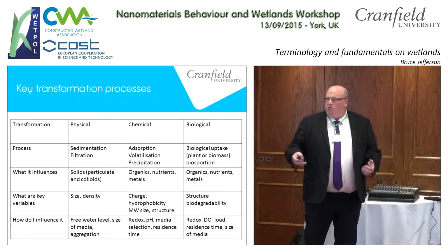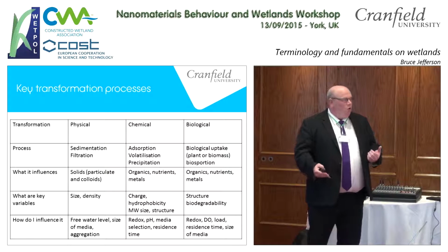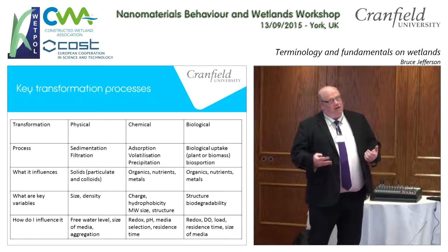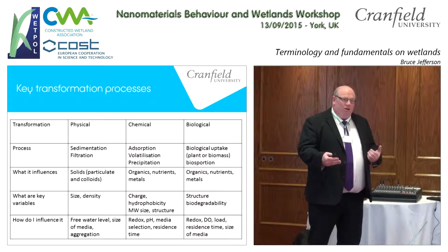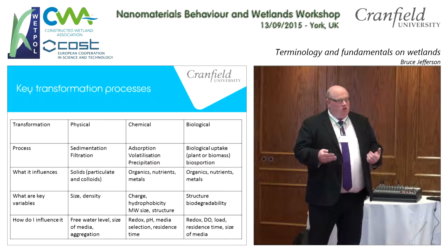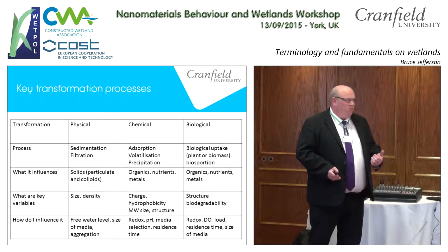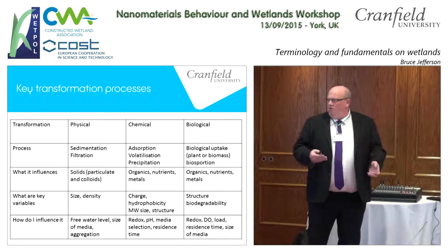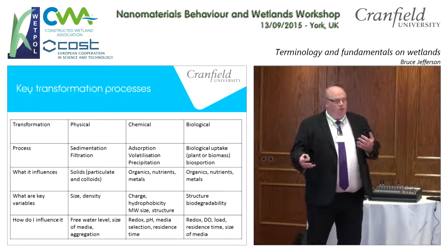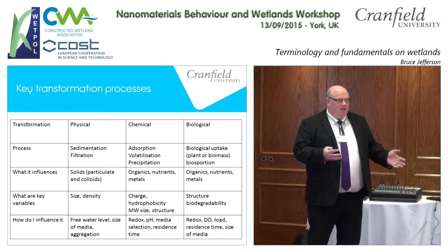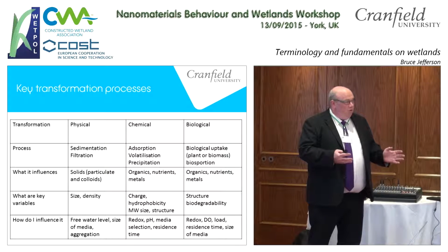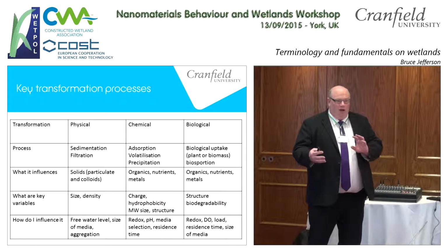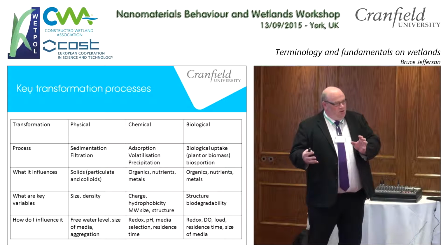If we go to the chemical type systems, we're talking about absorption, obviously some gas stripping depending on the chemistry, and in some of the newer type systems, especially around phosphorus, precipitation is becoming a very dominant mechanism in those pieces of technology. And then we've got the biological processes. This is really the combination of plant and biomass uptake. In the natural systems, probably quite heavily plant oriented. In our constructed treatment wetlands, much more biomass oriented.